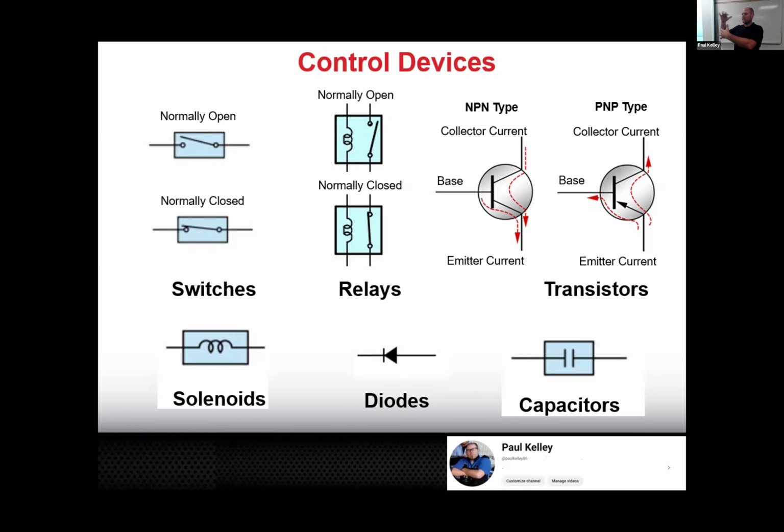At that point, you're no longer able to really charge your battery. If your voltage drops from 13.9 to 12.5, you'll visibly see the lights dim in the car. Electronic accessories may start to malfunction. So if every time the beat drops, your lights go dim and stuff, you think that's going to be acceptable to most drivers? They're going to think that you're flashing the high beams every time the boom boom kicks in, right?